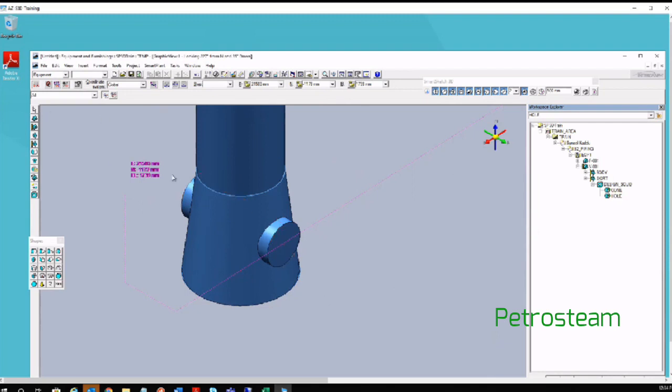After we have added the shape, till now it's a positive shape. If you select it, you can see it's through and through. In your graphics, it is visible through and through. There is a positive shape which is projecting outside. Now, how will you make it negative? By default, when you place any shape, it will be positive.